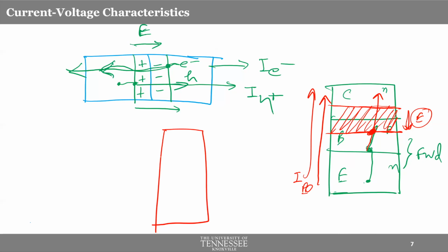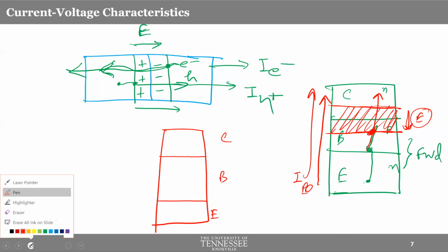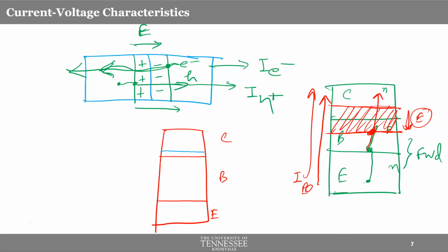Again, common sense. Emitter, collector, base. Imagine if you have a thinner depletion layer like this, electrons from the emitter go inside the base, and then gradually diffuse all the way to the collector. Okay, now compare that with